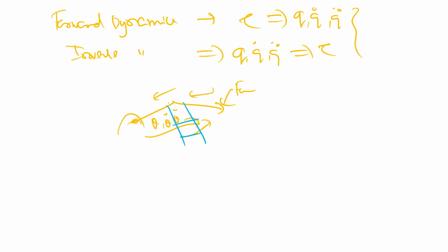In each joint, you have a motor, gear, and sensor. You have to give the torque to the motor accordingly. To find out the torque, we need motion, velocity, and acceleration. For that, we have to learn dynamics. Dynamics is a mathematical model which gives a relationship between the torque and the motion. The dynamics can be given by two models: one is the Lagrangian Euler model, and the other is the Newton Euler model.